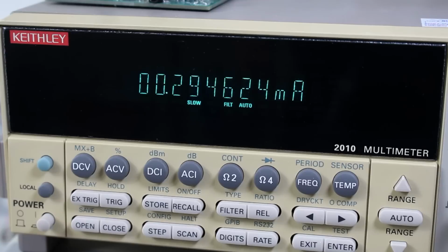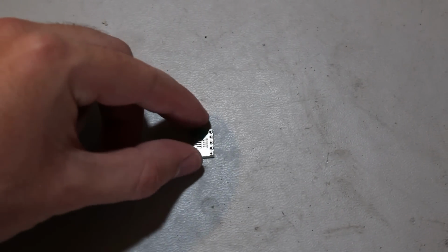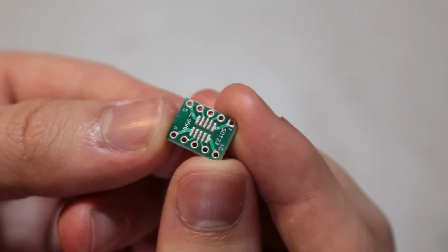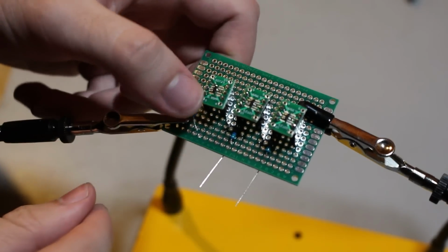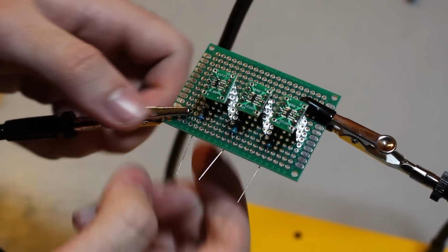This shouldn't be an issue though, since we are aiming for an identical but constant current from these devices. To get even better results, we should also degenerate our reference transistor. But at this point, I think it's safe to say that we've outgrown the breadboard. To get a proper demonstration of how well this degeneration improves matching, I got 3 of the MOSFETs that I will use in the final design, which were these small SMD types. I put all 3 of them on these adapter boards and put them on the circuit together on the prototyping board. This time, all of the transistors have 56 ohm degeneration resistors.